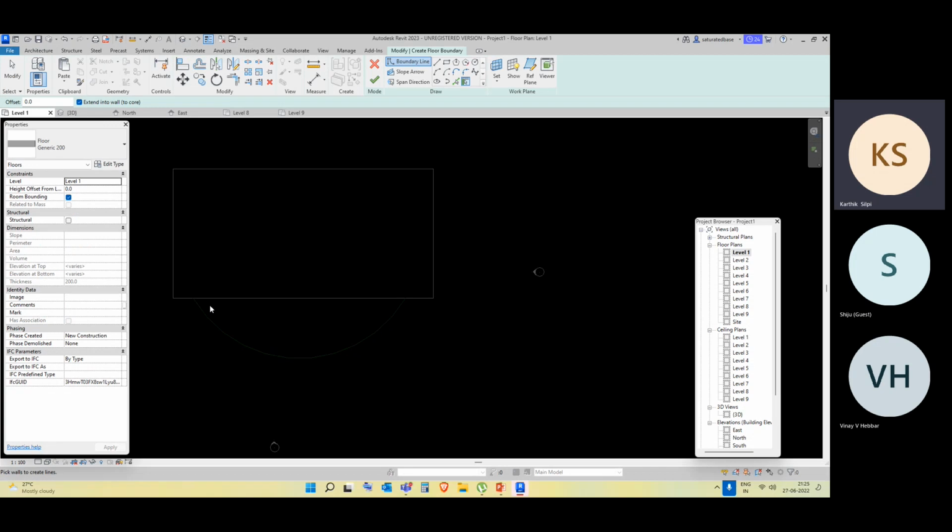So my requirement now will be, say for example, if I want to give a 3000 mm ramp, 1500 this side, 1500 this side, this is a reference line, and if I draw 1500 both sides, that will be 3000 mm. So that is what I'm going to do. I'm just going for pick line with an offset of 1500 mm.